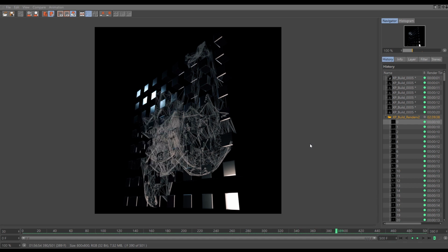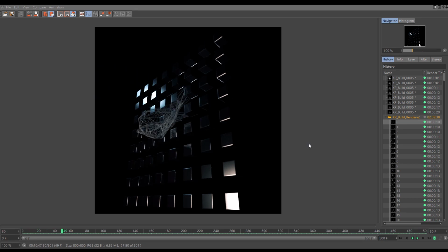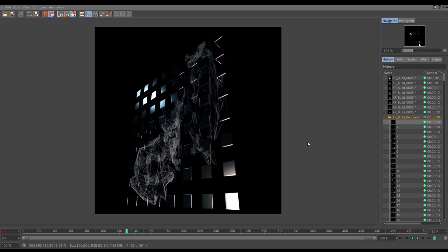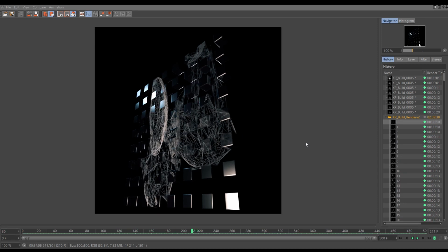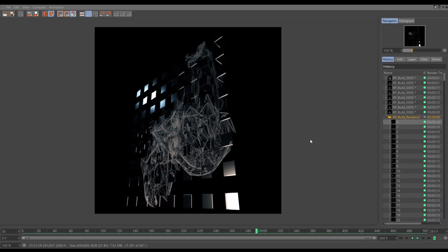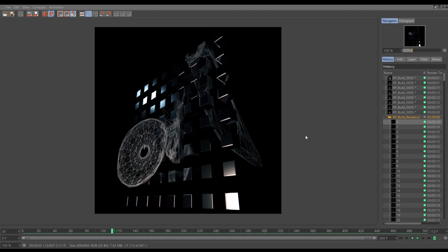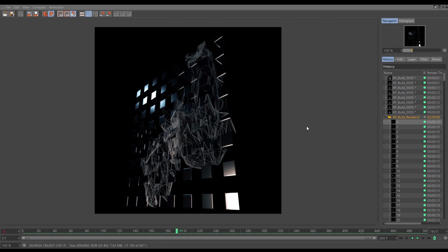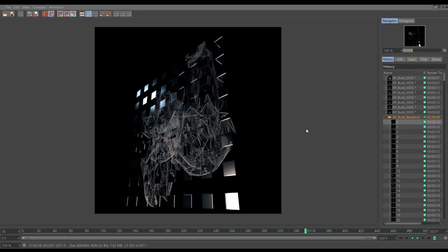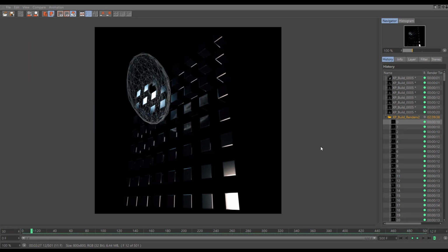A couple of things to note with this technique. The problem with rendering constraints in this way is that the constraint itself isn't dynamic, so you are going to get some intersections between the trails and the cubes, the collider objects. It's only the particles themselves which will collide accurately with those. So depending on the scene, that may cause you problems, but with lots of very wispy web trails like this, I think depending on the angle and the camera position, you can kind of get away with that. I think it still looks very effective, and you don't necessarily notice the fact that there is geometry and trail intersection. But fantastic technique. Go away and try it on your scene.